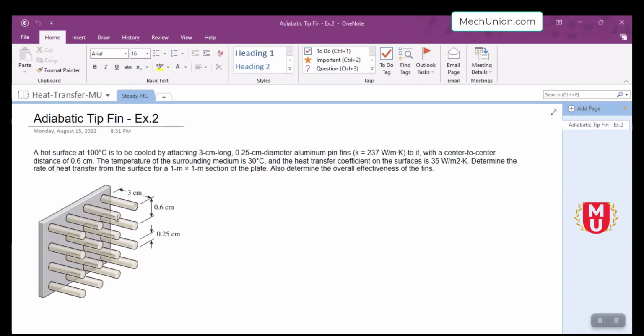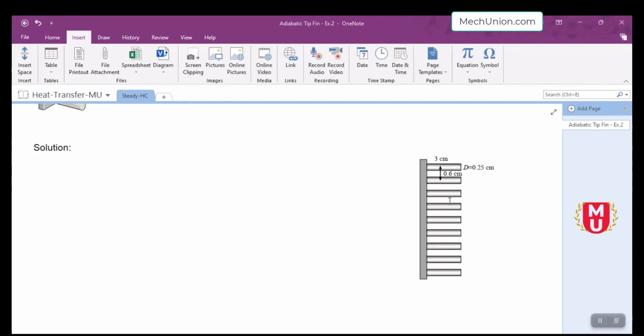The heat transfer coefficient is constant and uniform over the entire fin surface. And 5. The thermal properties of the fins are constant, and the heat transfer coefficient accounts for the effect of radiation from the fins. A figure from the side view has been shown here.